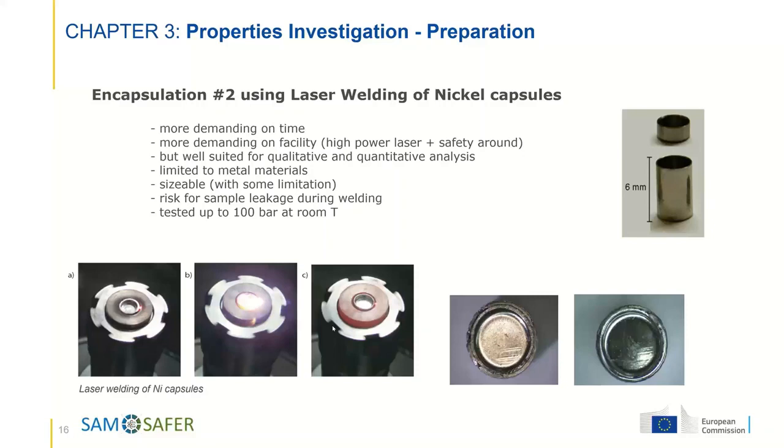It's a very tiny crucible. We do it because here we want to use these kind of crucibles, for instance, for quantitative analysis of heat capacity, as I will show later. And there really the demand is for a lot of sample but little crucible material. That's why the walls are, I think, 0.2 millimeter thick, so that we have this ratio of sample versus encapsulating material as high as achievable in principle. So this is another type of encapsulation that we are using. Important is, after we encapsulate the material, to test it.